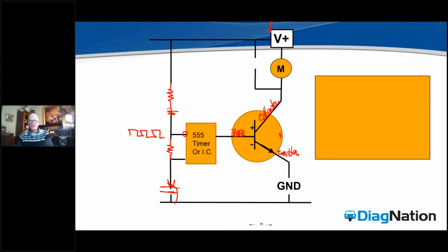It is then passed into the device. Our pulse width modulation is now going to be turning this transistor on and off. And as it does so, the current is allowed to flow through from the ground, or from the voltage, depending on where this is configured, up through to run the motor.